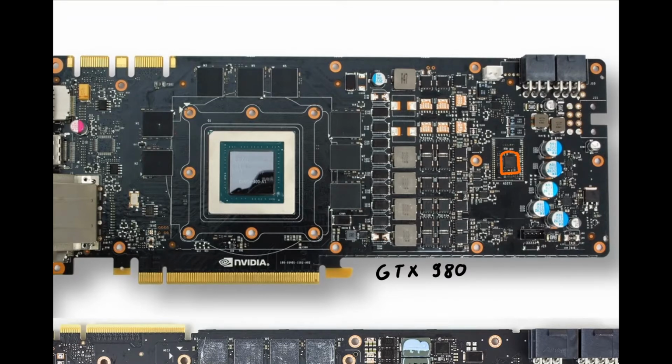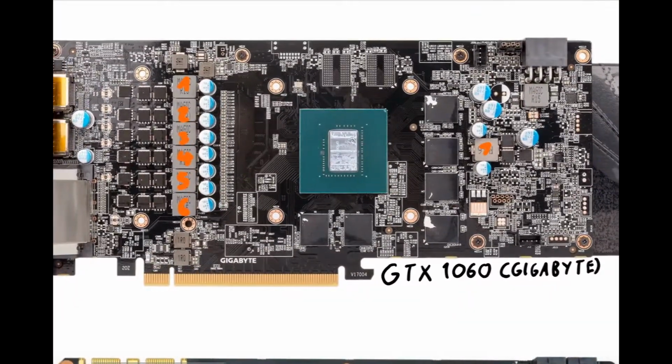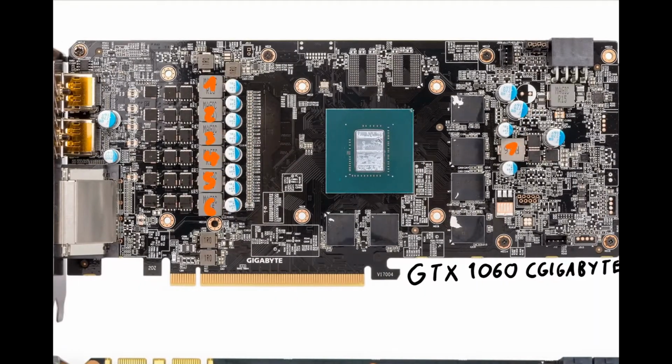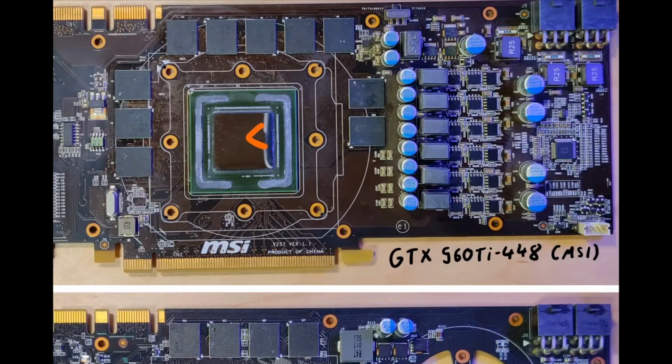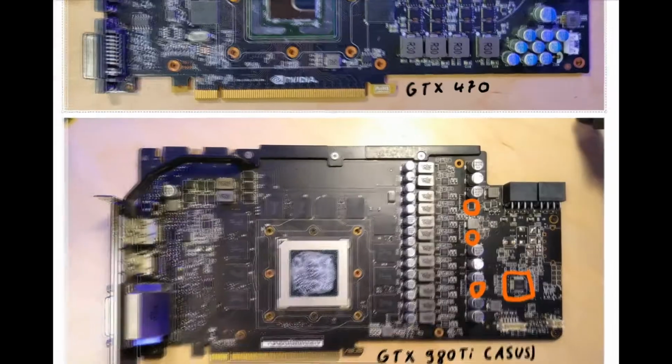I actually don't know for the 900 series, but on the 700 series, which used very similar PCBs, it was the NCP4208. And basically by looking at that little chip, you can't see it on this card because it is very likely on the back. Here we have another PWM controller. This card also has it on the back. It's about here on the back, and I already showed you the PWM controller on there.